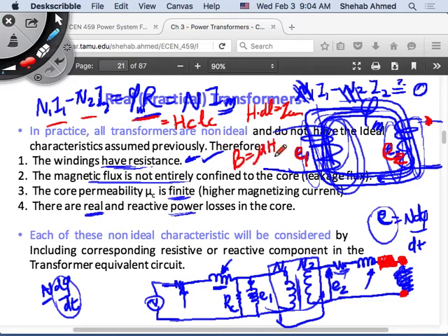So we said that H, the magnetic field intensity, is due to some magnetic flux density in this core created by the flux flowing. And we assumed mu was a fixed number, right? Is this a fixed number? No, it's not. Is this linear? No, it's not. There's a BH curve involved as well, right? So what happens due to that? We didn't consider it in this model.